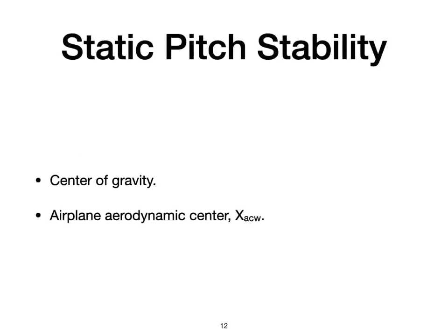Static pitch stability. For static stability to be present, any change in angle of attack must generate moments which oppose the change. In other words, the derivative of pitching moment with respect to angle of attack must be negative. The magnitude of the pitching moment derivative changes with center of gravity location.